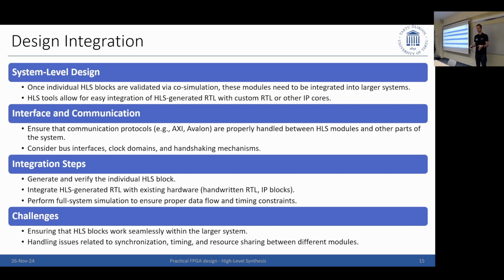I have my IP core. It will run, I'm intending it to run at this frequency, but this other one doesn't work, so a different one. Then you still need to potentially implement your clock domain crossing in hardware design. So something to be aware of. Essentially the same design rules as in a hardware design apply for an HLS IP core. It's not magically doing everything.